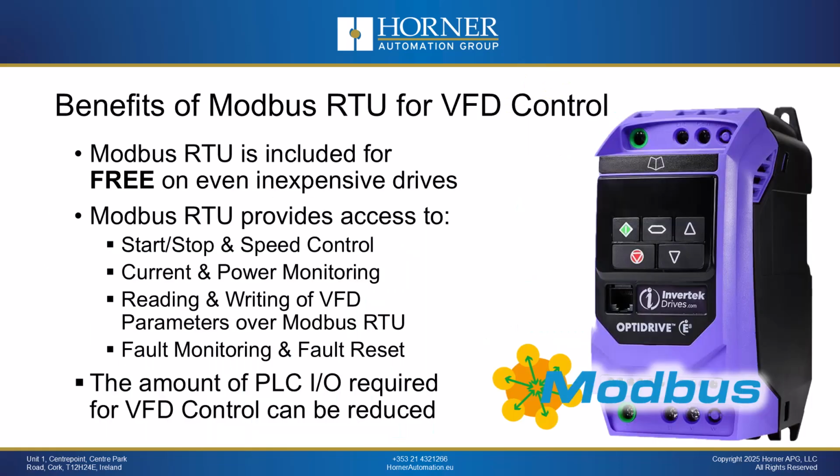So now we have discussed some of the background on Modbus, how it's organized, how it's numbered, and what function codes are supported. Now we will look at some of the benefits of using Modbus RTU to control a drive. With most drives, Modbus RTU support is included for free on the drive. Modbus RTU provides the ability to start and stop the drive, control the speed, and monitor power and current data. It also allows you to read and write individual drive parameters if needed.